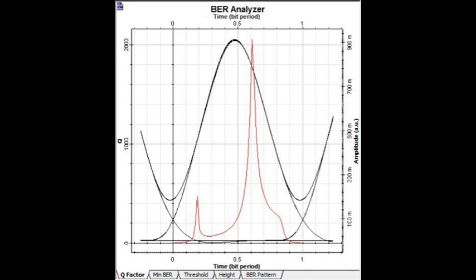At another point, when attenuation is up to 500 dB per kilometer, the condition at range 1 meter shows the maximum Q factor is 5729.77, minimum BER still 0 value, and eye height is 1.084947. Compared to 5 meter